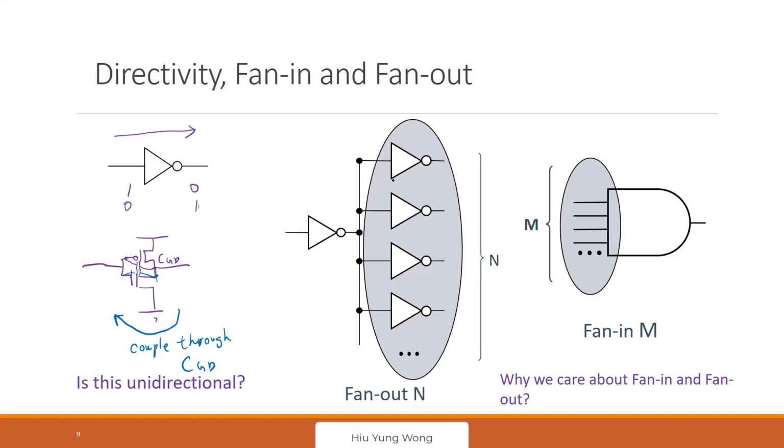So he already sees that this is not just a triangle. This is actually a transistor. And when it is on, let's say when this is 0 volt, this is off, this is VDD, and I'm relying on this guy to charge N times CG. I should assume just CG, right? CGS. I'm relying on this to charge them. And this is limited to the ID set. So it takes time to charge, right? What if it is not limited by ID set?